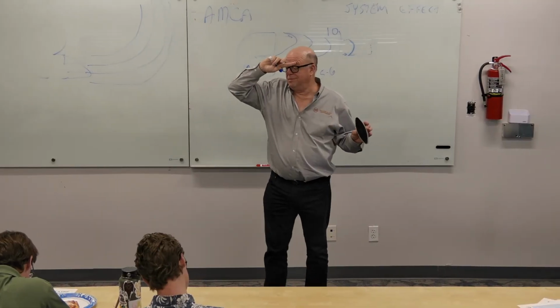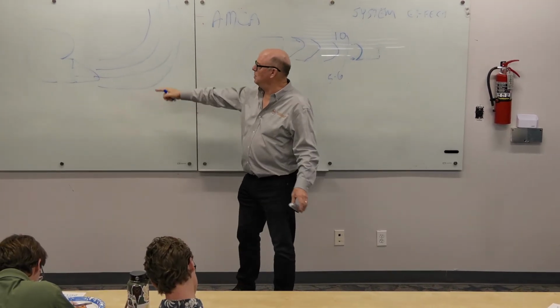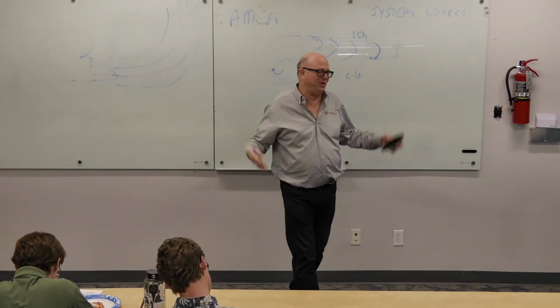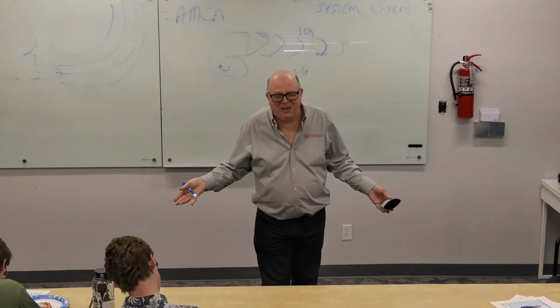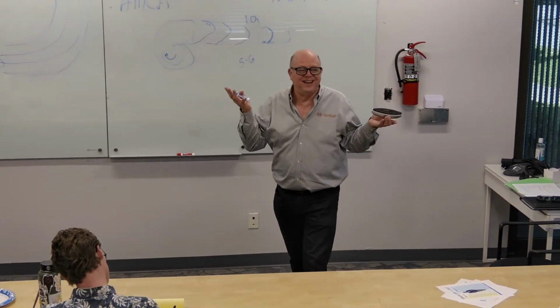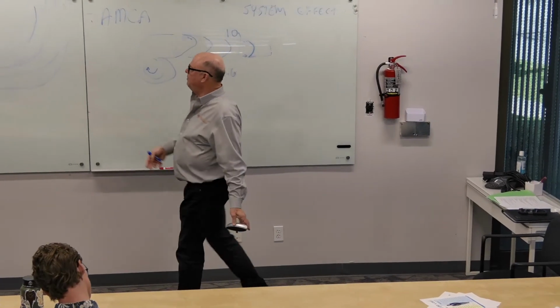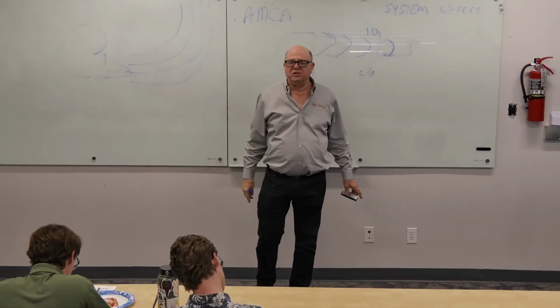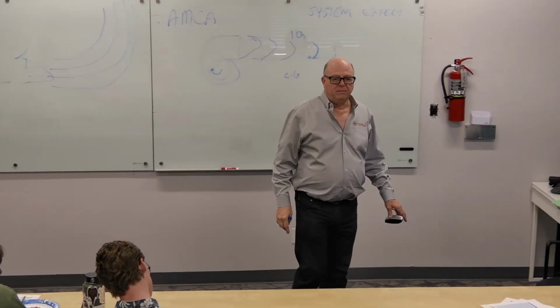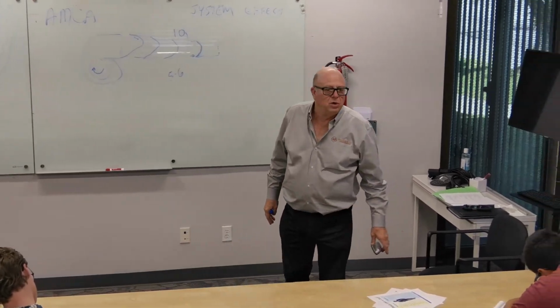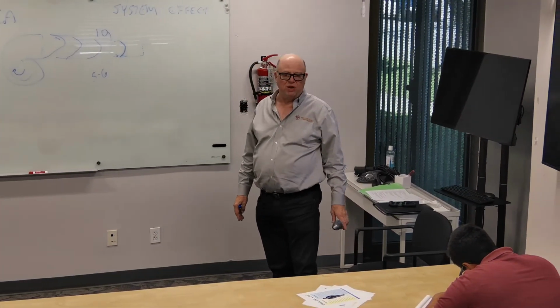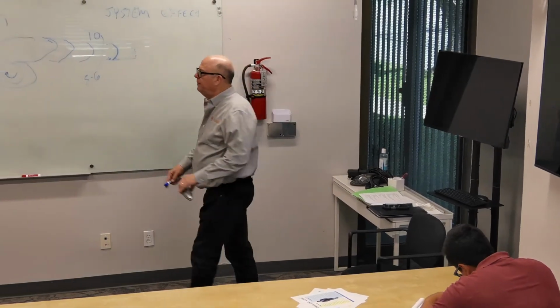Now, you get a diminishing return thing. Could we put 20 splitters in that elbow? Sure, but would we really gain anything? No. So, you know, if it was a really tiny duct, maybe 1 splitter is all you need. Maybe as it gets bigger, you'd want 2 or maybe 3. I've never seen really more than 3.